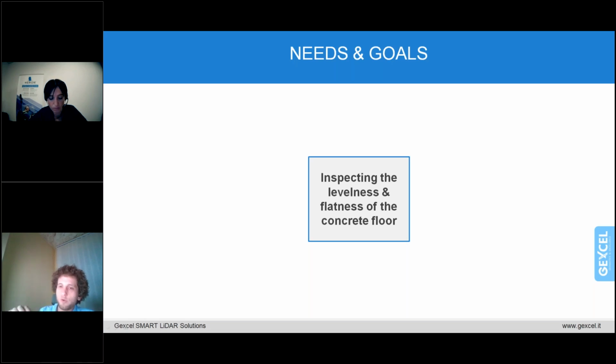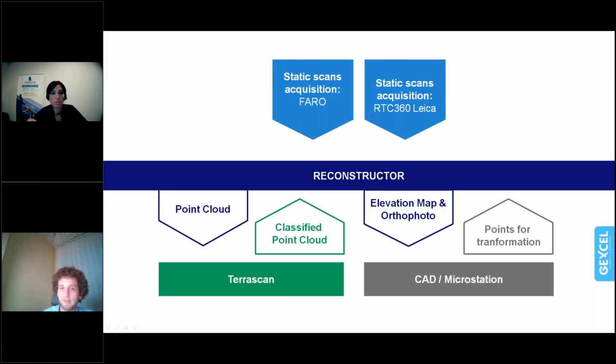So whenever you consider a forklift going up and down with the highest speed possible to get things faster and faster, every bump you have on the concrete floor might have an amortization effect on the wheel bearings, and this is the main reason that logistics storage companies have quite strict restrictions for floor flatness and levelness. There are standards for this: in the USA ASTM, in Great Britain TR34, and in Germany the DIN.